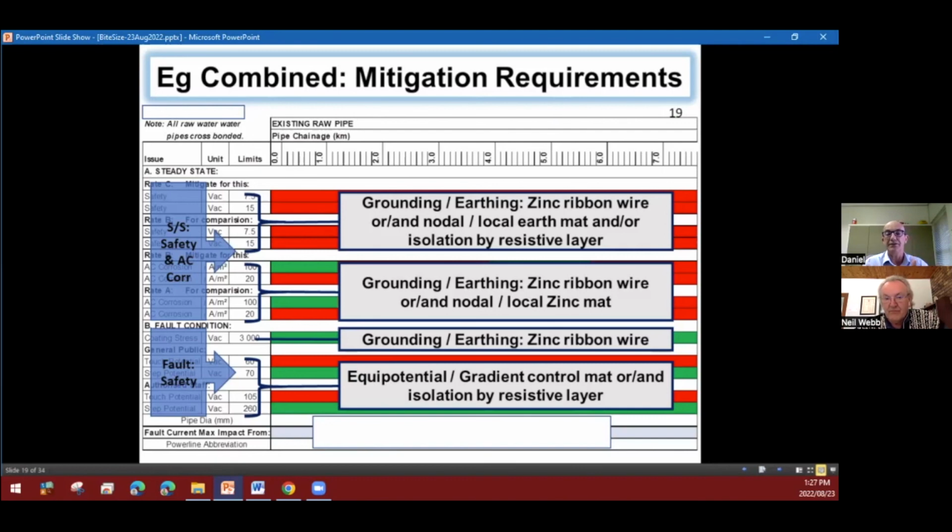So in this case, we decouple our grounding system from the pipe, and we install a decoupler between the two. This decoupler will DC decouple, so the CP system doesn't see this bare metal lying in the ground. It's DC decoupled, but it retains AC coupling. It's much the same principle as a battery with the plates. It's like a capacitor which conducts AC and blocks DC.